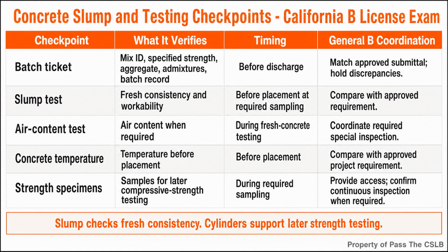Imagine a ready mix truck at the curb. The crew wants a mix that will move easily, fill the forms, and finish without a fight. Somebody reaches for a hose because the load feels stiff. That moment is where supervision matters. Extra water can increase slump, but it also changes the water to cement ratio. An approved water-reducing admixture can also increase slump, but it does so without simply pouring more water into the mix. Those two loads might look equally workable for a few minutes, yet they are not the same concrete.